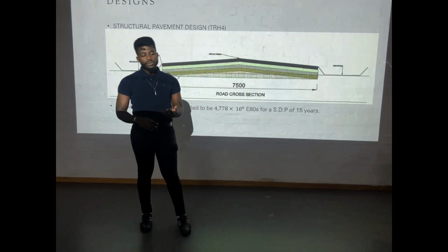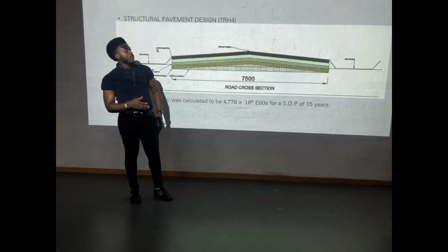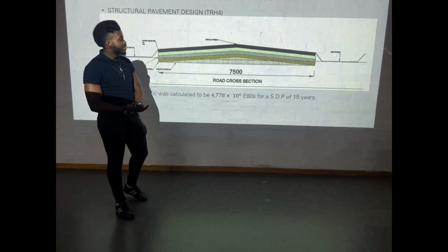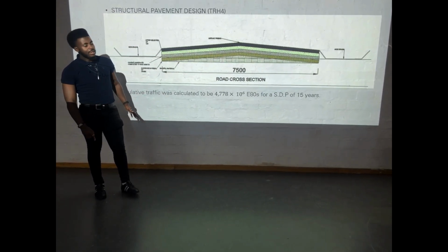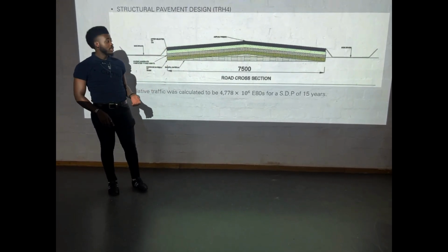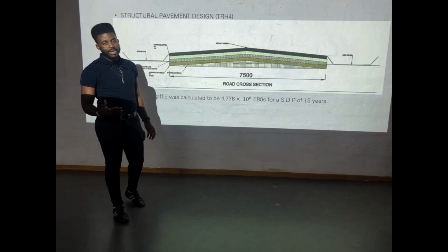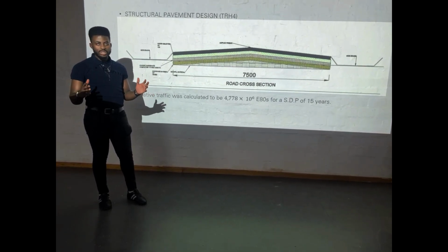So taking that into consideration about the terrain for design, we are able to come out with this particular pavement design. This pavement design consists of different layers. Primary layer, the first 3 layers, which is our premix road, the following layers, and then we also have an additional pioneer layer, which indicated that our area is in a wet region.